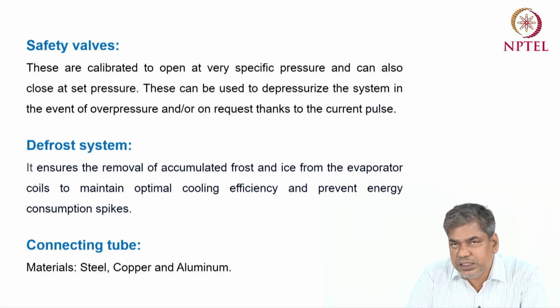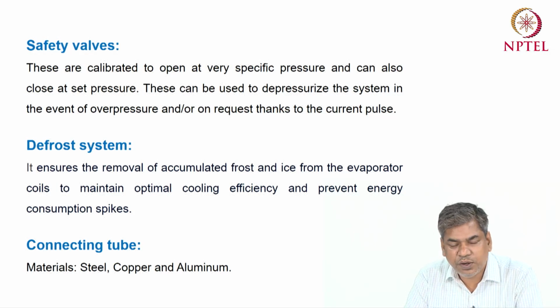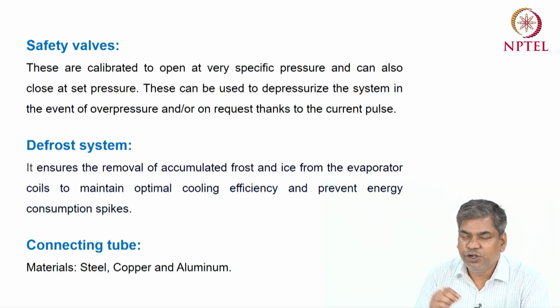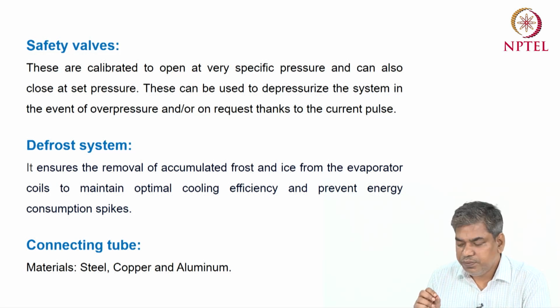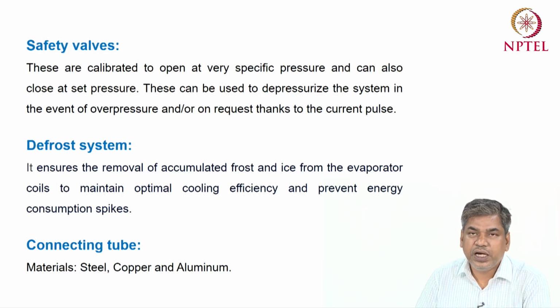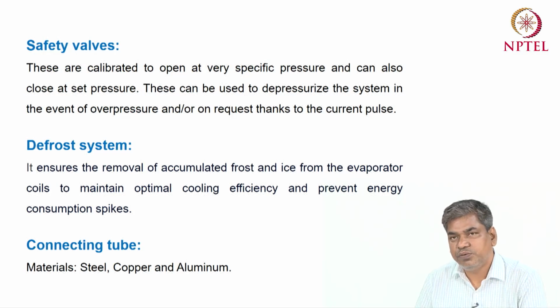Another thing is that in the case of a fin tube type evaporator, where air is flowing in between the fins, those channels are very narrow. So if ice forms and blocks that narrow channel for the airflow, that will block the airflow also, and that will also degrade the performance of the system.